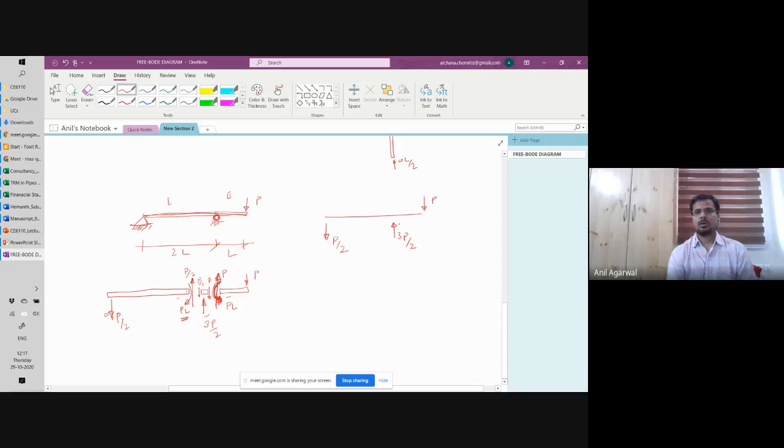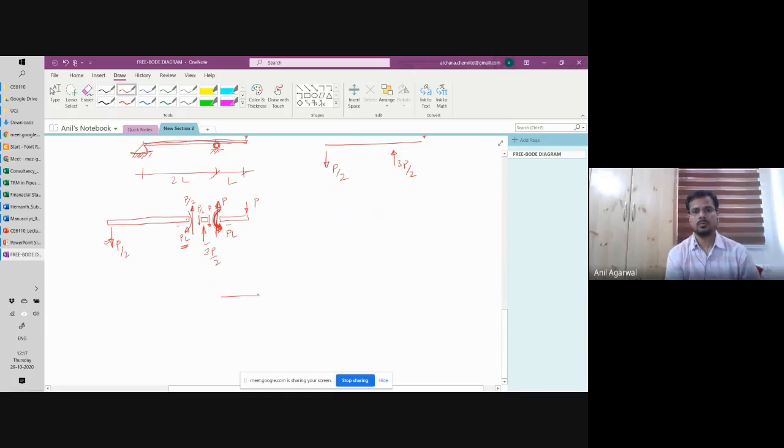All right, so you've got these external forces. From here, you can very easily calculate the bending moment diagram. For this part, you've got 0 moment here and PL moment here. Now, when you're drawing the bending moment diagram, you have to look at the bending moment. For each small component, you have a sagging moment, right?